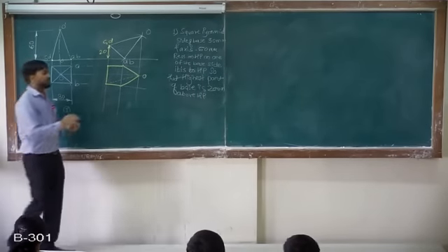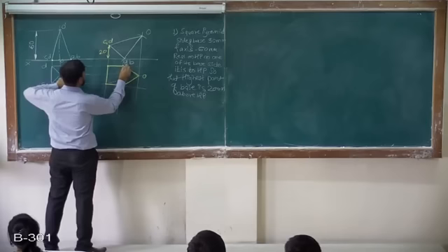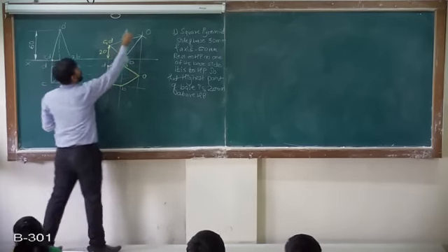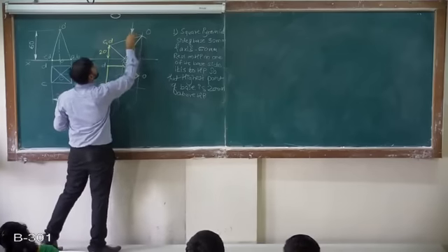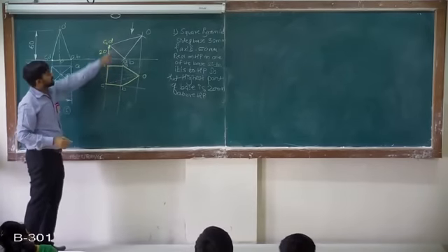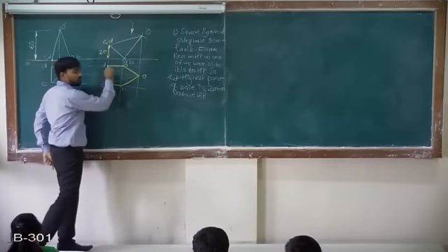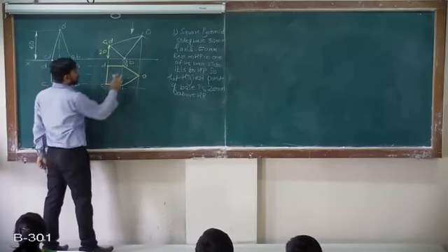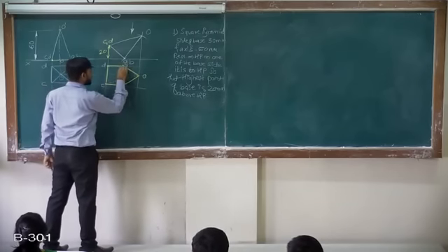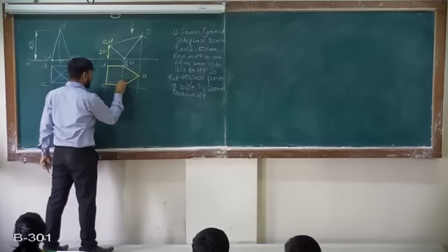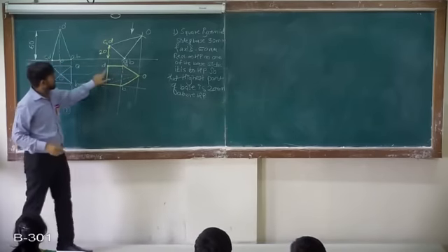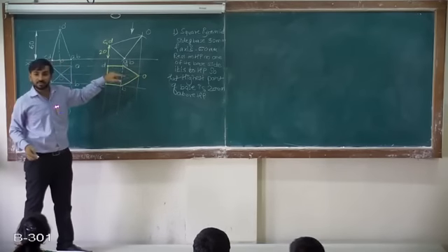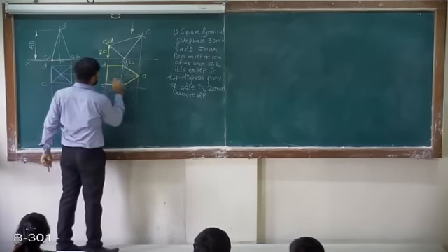Now what I will do, I will just join, let's say this point is point A, B, C and D. Here the observer position is this, the line passing through the nearest point, let's say O, as outer edges, this I have drawn as a continuous line, this AB, so this I can draw as well as these two edges DO and this, they are also not visible. So I need to join this with these hidden lines.